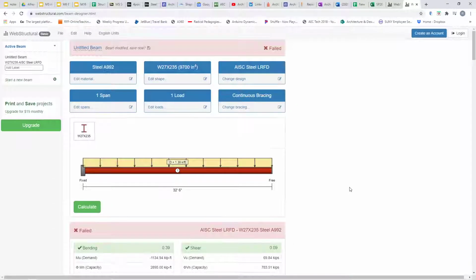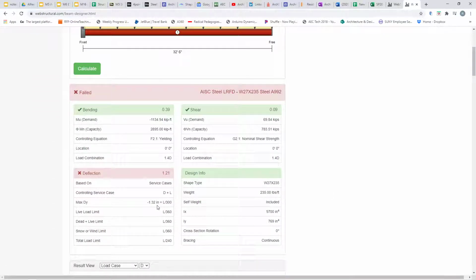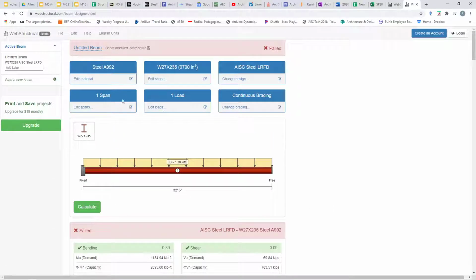I obviously don't want to, we're still not meeting the goal, but we're very close here. But this is a beam that is 235 pounds per foot. And what else is weighing into this, pun intended, is that it's also taking into the weight of the structure in that calculation. So every foot we're adding 235 pounds. So we've got a lot of dead load in this element.